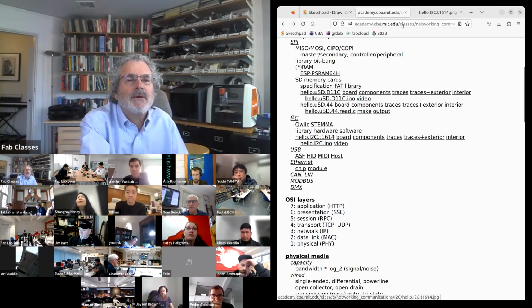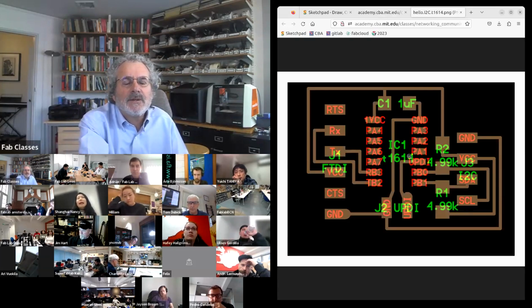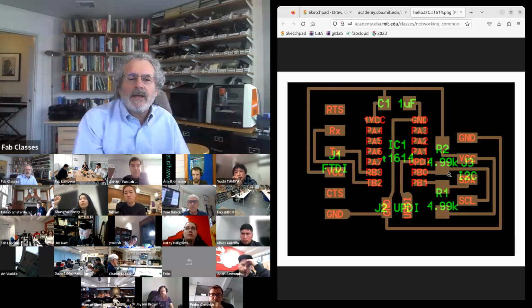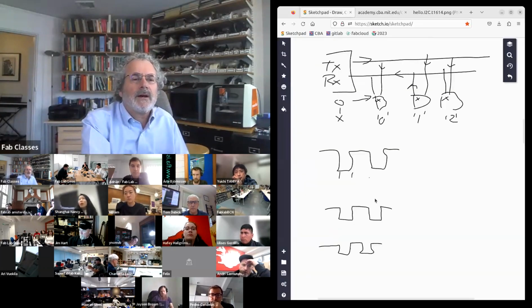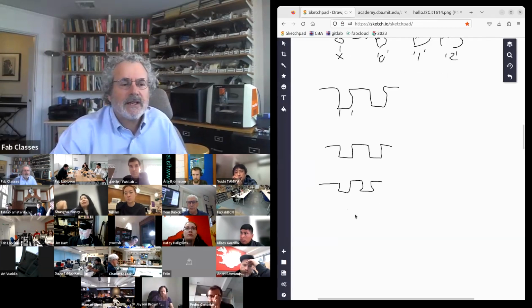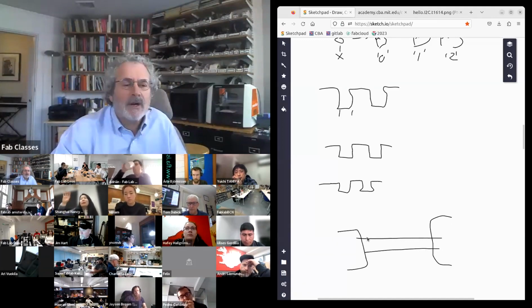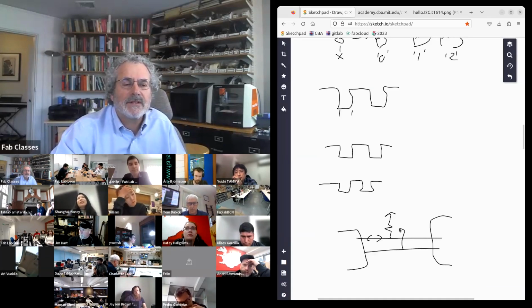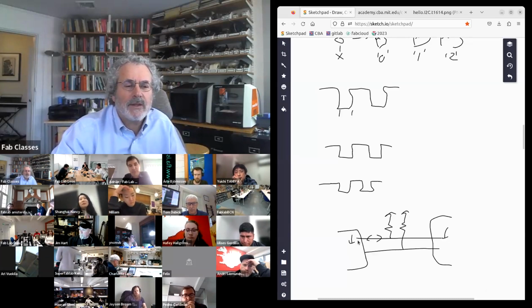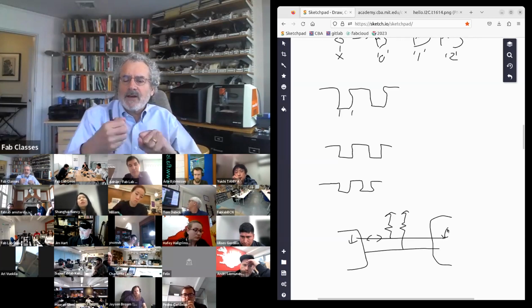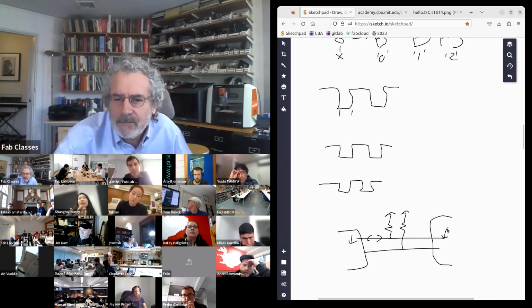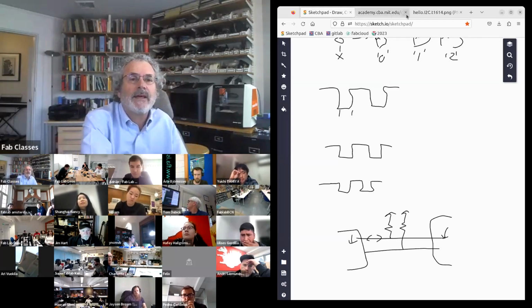So this example I'll show is, here's a processor. I've got I2C connected. You'll see these two resistors. The way in I2C, we've got a line shared between the two sides, and signals can go in either direction. So the way that's handled is you have a pull-up resistor that holds them high, and then either side can pull them down when they want to talk low. So you don't have to worry about fighting over the line. You have pull-ups that hold it up, and then you have pull downs.